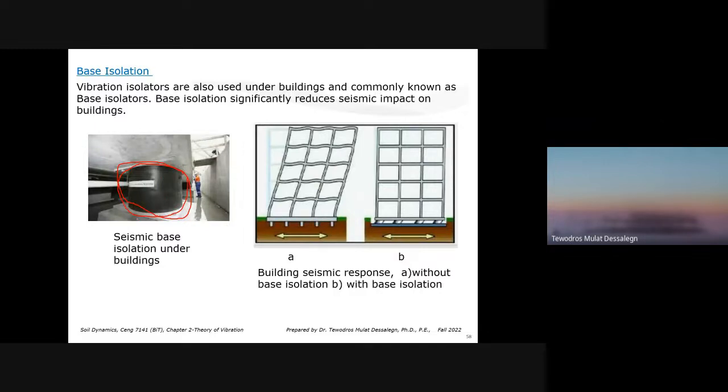So what it does is, let's say you have a ground motion like this. If you don't have any base isolation, the way the building deforms is like this. See it in one cyclic phase. When it bends, because the foundation is rigid, then you have large bending on this one, because the building is trying to bend like a cantilever.